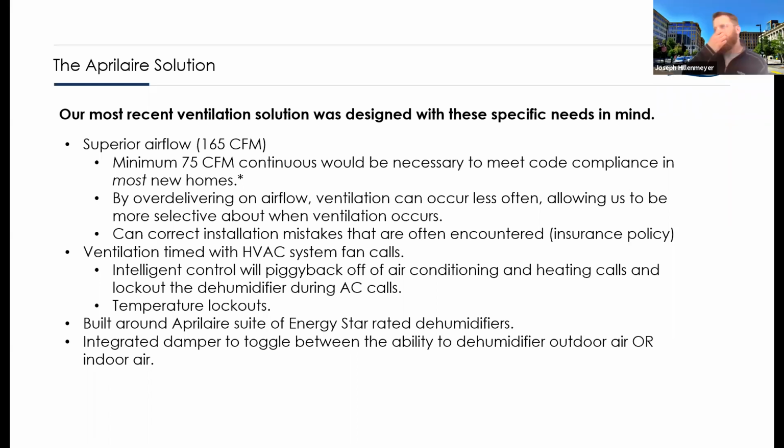Yeah, and the other thing that's really important with dehumidifiers is capacity. I mean, just like any other equipment, if it's undersized, it's just going to cycle and run more often. So even if it has better energy ratings, on paper, if it's running all the time, that's out the window. So these dehumidifiers that have a large capacity, this is like 100 pints. If you looked at something at a retail location, you would be closer to maybe 50 pints per day, perhaps less than that. Yeah, that's probably not going to handle the load in most places.